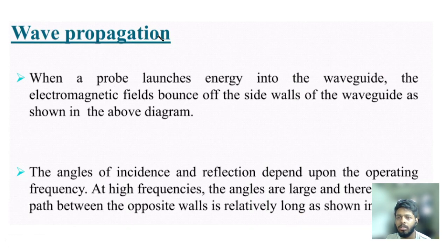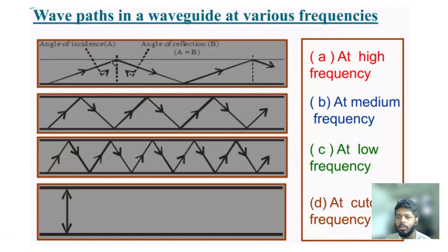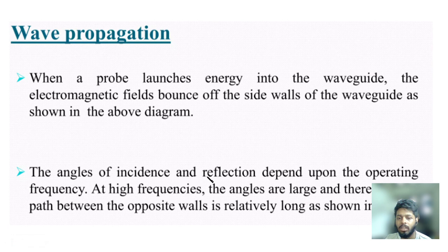That is wave propagation. When a probe launches energy into the waveguide, the electromagnetic fields bounce off the sidewalls of the waveguide as shown in the diagram. As you can see in this diagram, the angles of incidence and reflection depend upon the operating frequency.